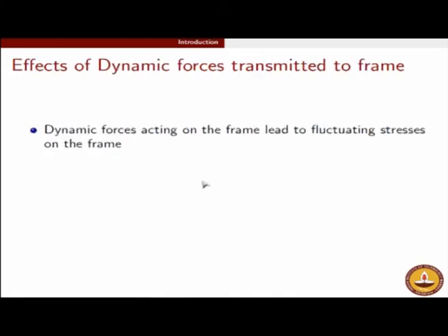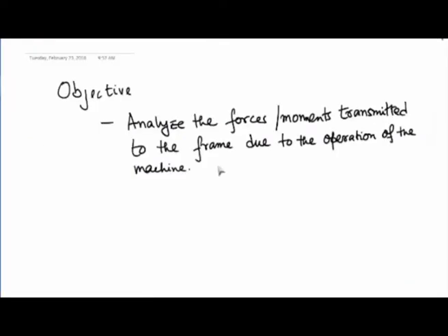Well, for that we must understand the effect of dynamic forces transmitted to the frame. Just a couple of minutes ago I emphasized to you that if it is a static force which is getting transmitted to the frame, it is going to create a static stress, a static strain, and you will have some theories of failure to predict whether the frame will be able to endure that kind of loading. But if it is dynamic forces acting on the frame,